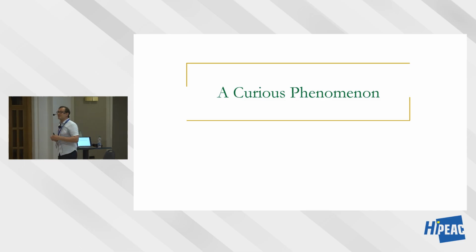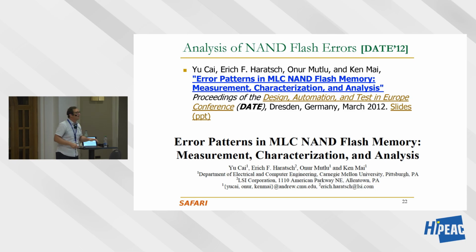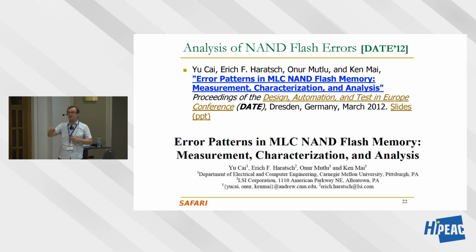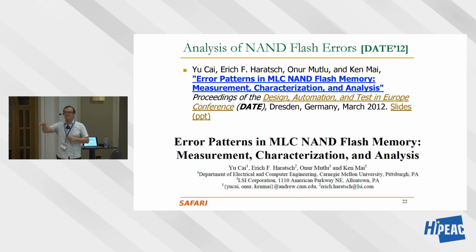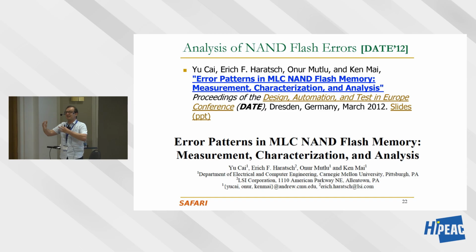So while we were doing all of this, we also asked the question, okay, DRAM, and actually, in fact, in these papers, in flash memory, we saw a lot of read disturbance issues. Whenever you read a page in flash memory, you disturb other pages. So some bit flips happen. So you need to design your flash controller to fix those issues. Otherwise, you'll get bit flips in storage. But in flash memory, we have a beautiful interface, meaning that the flash controller can be designed to be completely flexible. It can do anything it wants to fix all of these issues. In DRAM, we don't have that interface today because somebody designs a memory controller and it has a very rigid interface. So we actually did a lot of studies to understand this read disturbance.